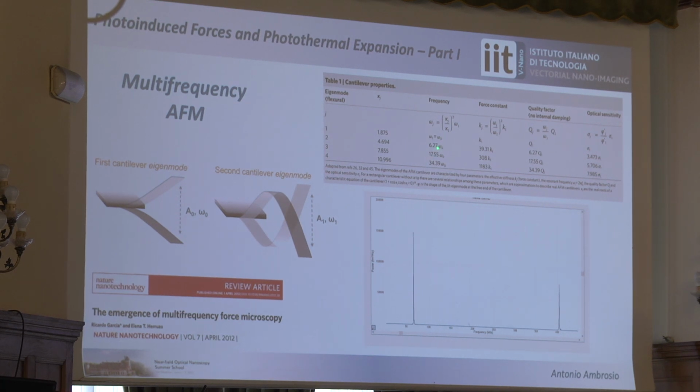And the third eigenmode is higher, and so on. And also, look at the Q factor. As you go higher with the mode, your Q factor increases, and also the effective stiffness of the cantilever increases by a lot, right? It's 40 times the first mode, and 300 more times in the third eigenmode, right? This is to keep in mind.